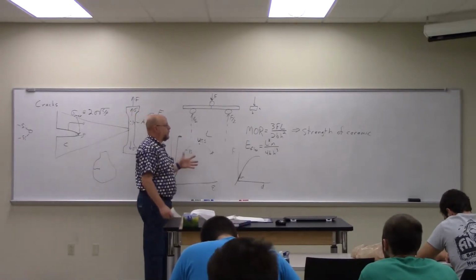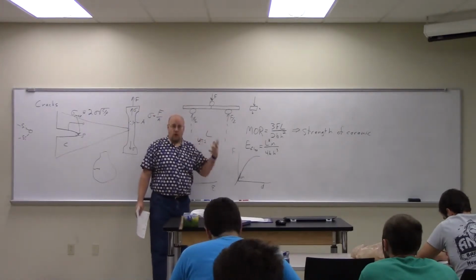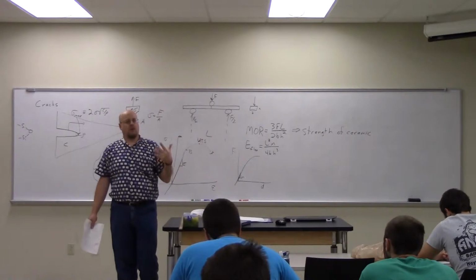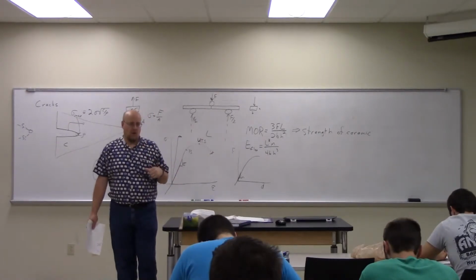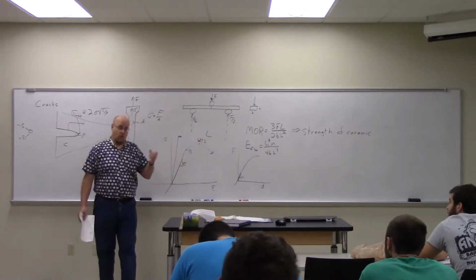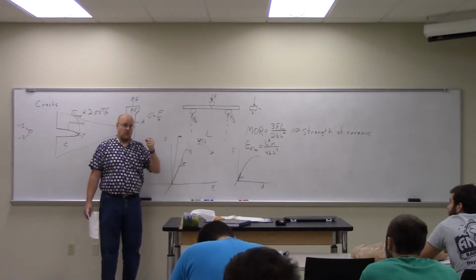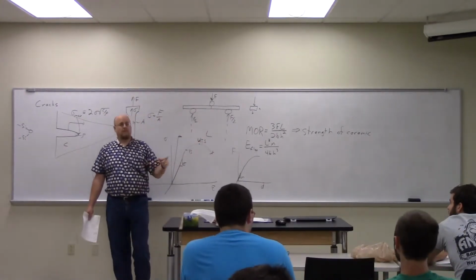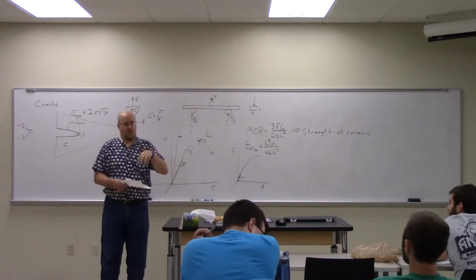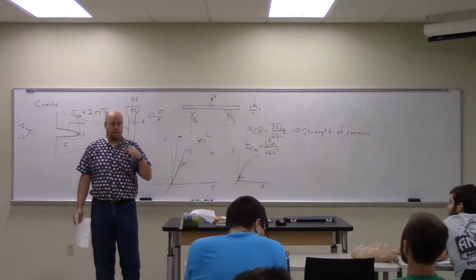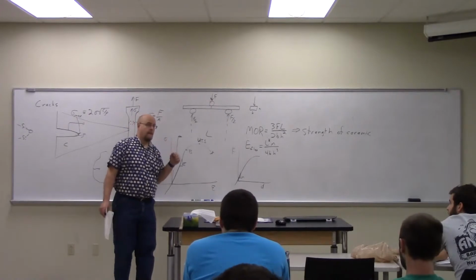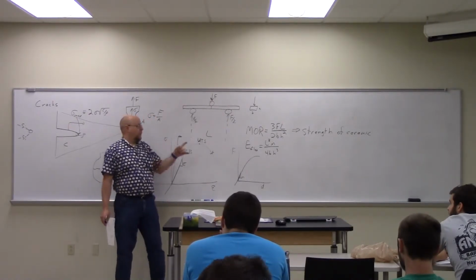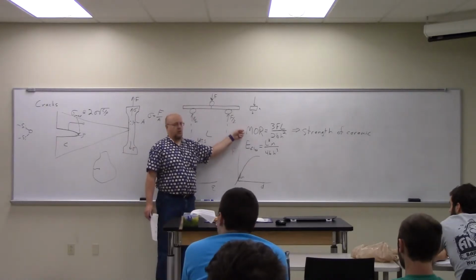It's just that they are both things that, for different reasons, you typically don't want to examine just in a tensile test. Okay. Ceramics, because it's really hard to grab hold of them and pull them in a tensile test. It's a lot easier to do this. And polymers, because they behave differently in tension than they do in compression. But we still use both of the moduluses for ceramics and polymers? Yeah. So this one's only used for ceramics.